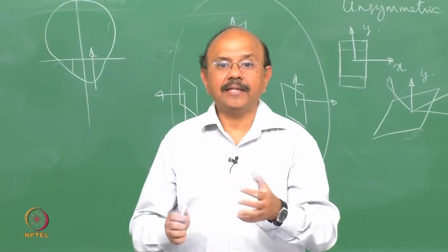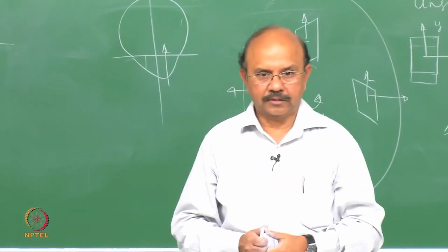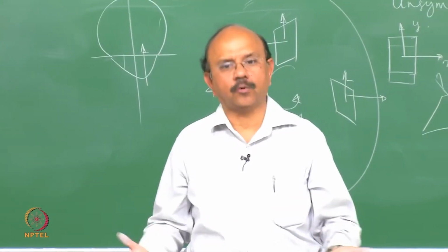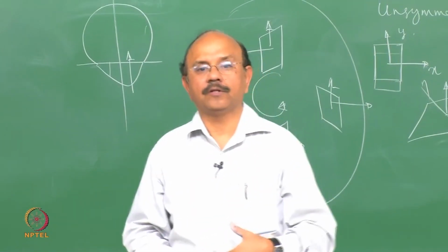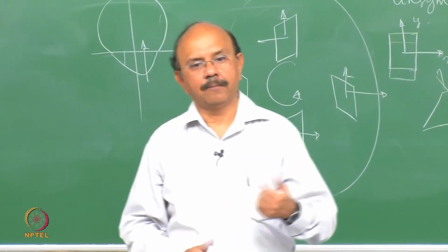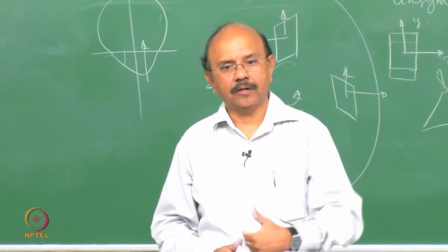Clear? So can I replace the complete contact pressure by means of an equivalent force? That's the question. Of course you will do it. And of course that's what we did for all the longitudinal forces, and that's exactly what we are going to do for the lateral force. So for the lateral force generation, we're going to look at the equivalent force as well as a moment, which we called the aligning term.